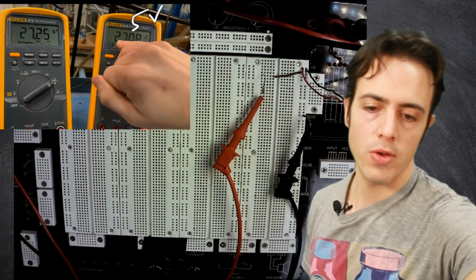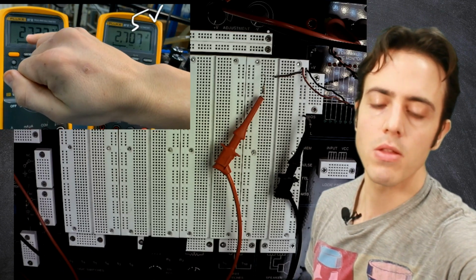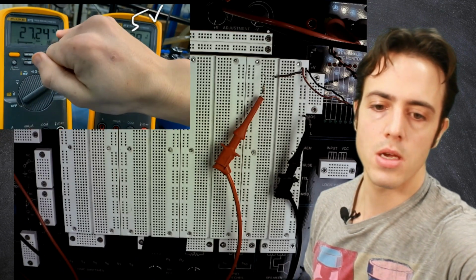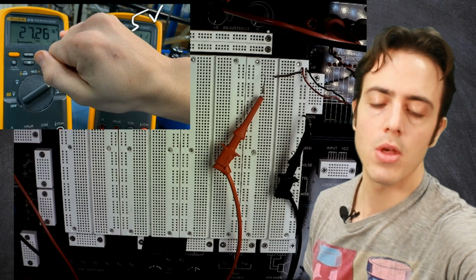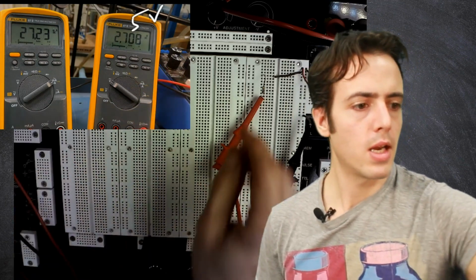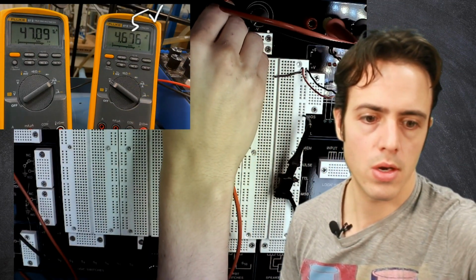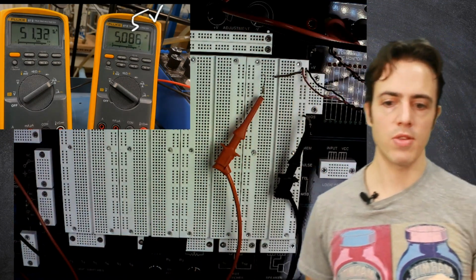So we've got 2.7 volts going in, and we've got 27 milliamps, and that makes sense because that's this number divided by 100 to get this one. Okay, that was my mistake with setting up how this works. Let's now increase the voltage up to 5 volts. So this is supposed to be the maximum that this resistor can take.